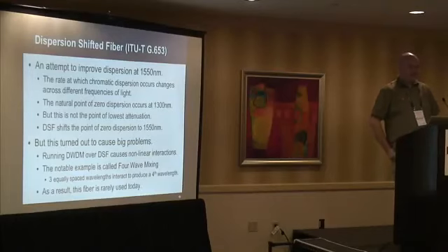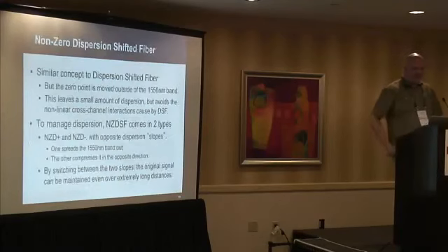People didn't know this at the time, but when you started running DWDM over just straight dispersion shifted fiber, when you hit the zero-dispersion point, you started causing a bunch of nonlinear interactions. What would happen is you would take three wavelengths that are supposed to be ships in the night not talking to each other, and they would interact with each other and produce a fourth phantom wavelength. A bunch of physics that's way over my head, but it just turned out to be a huge hassle. So everyone backed away from this very quickly and moved to something called non-zero dispersion shifted fiber.